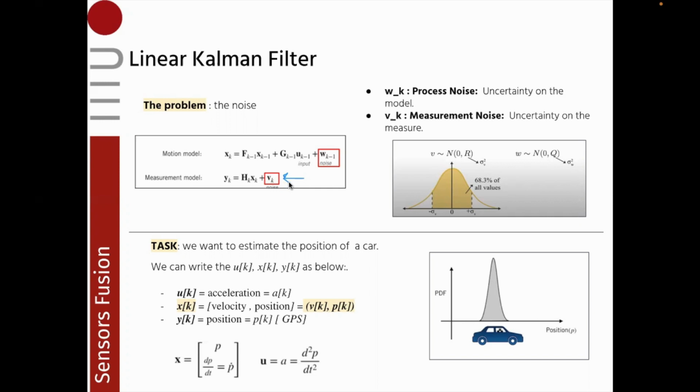Here we have a second type of noise, called process noise, which represents our uncertainty, our ignorance, about the evolution of the model itself. This is usually set as a Gaussian distribution, for which the theory tells us that, under this condition, the Kalman filter gets the best estimation performance.